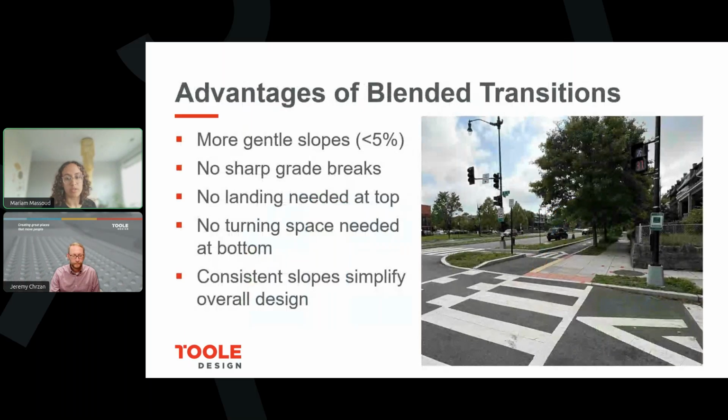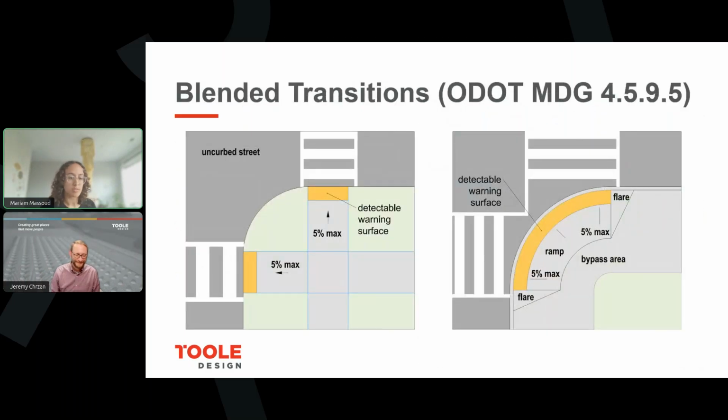On the left, is kind of similar to the curb ramp pictures that we've been looking at. On the right, these are also sometimes called fans or depressed corners. And although it looks similar to a diagonal ramp, it's not a diagonal ramp. First of all, because of the difference in slope, but then also because it doesn't require someone to change directions at the bottom of the ramp.